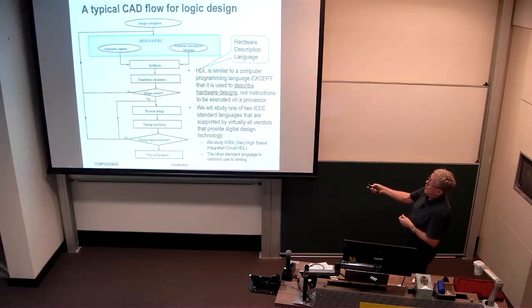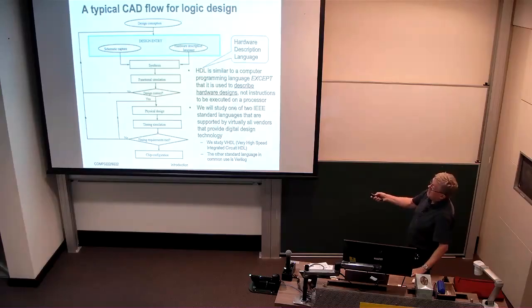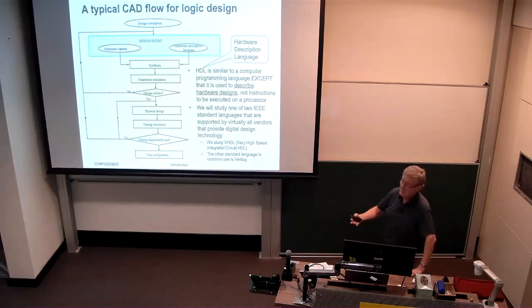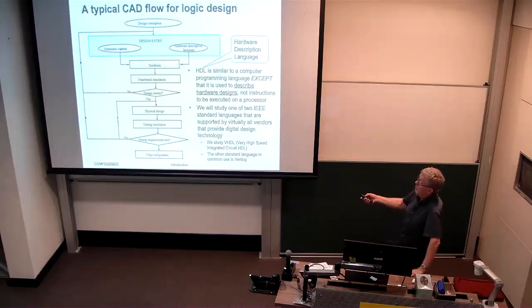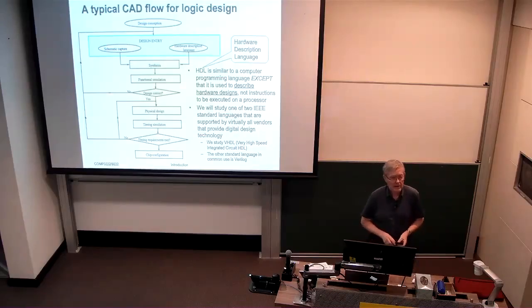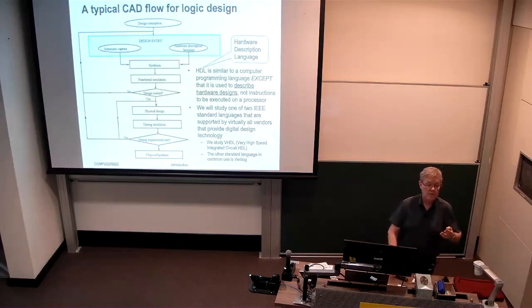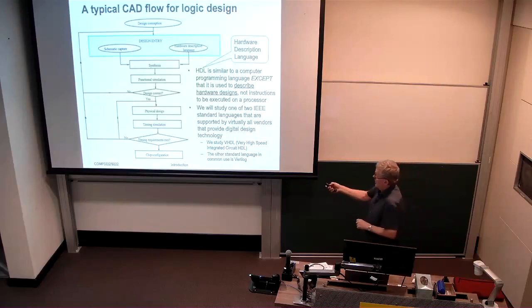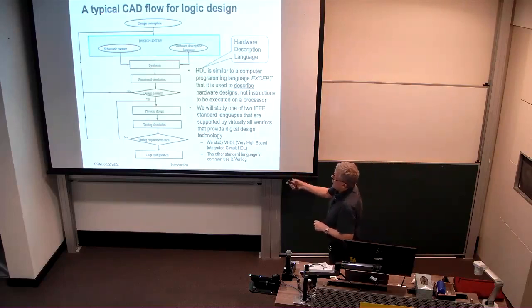Needless to say, when you have described your design at the top here, that then gets passed through a compiler effectively, although there are other names given to it. Synthesis tool is common, to synthesize what's known as a netlist. And a netlist is a logical description of your circuit. Think of it as a circuit diagram. That's all you really need to know. That's what's generated by the compiler when you go through the synthesis step.